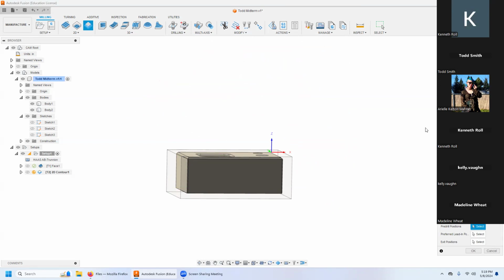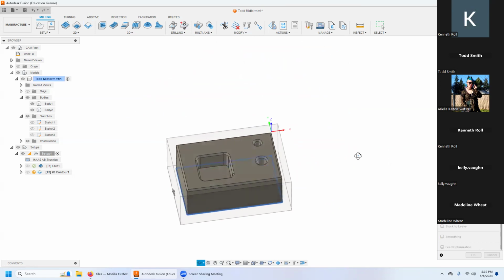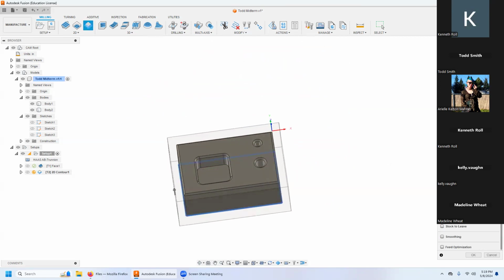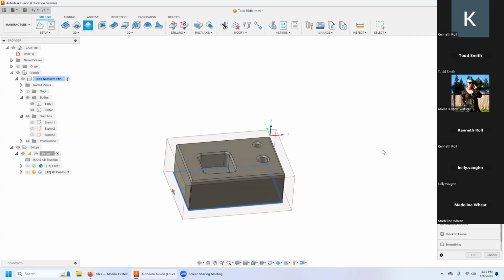We're now going to groove on over to linking. Oh, wait, nope. I need passes. Sorry. Accidentally skipped passes. So, compensation type. Big deal here. I enthusiastically recommend wear. You will be glad. I'm going to skip making sharp corners for now. Sharp corners can leave burrs on the vertical corners if we're not careful, but sometimes Fusion will round that corner off a little bit if we don't. So we're going to see what it's doing this time.